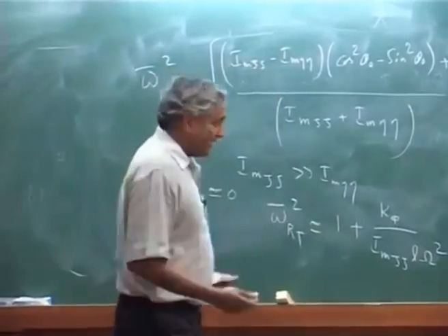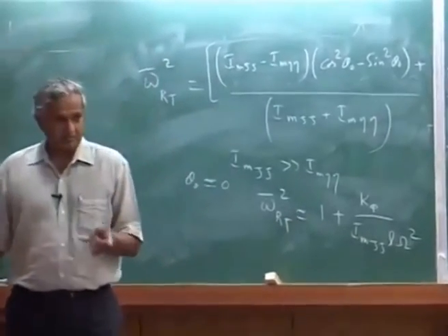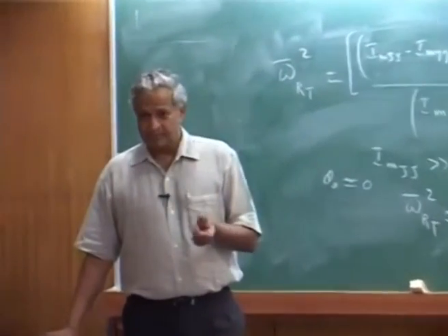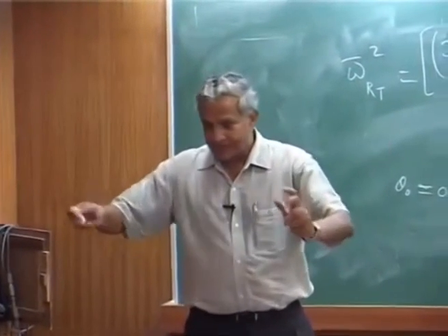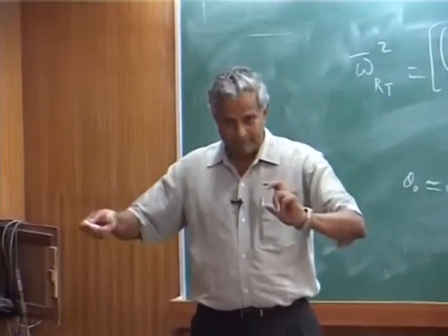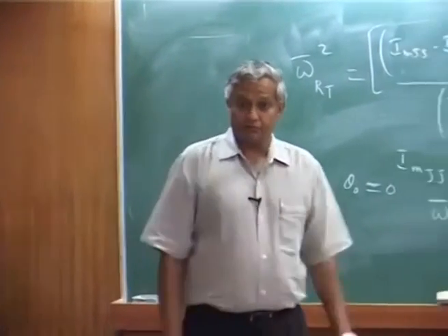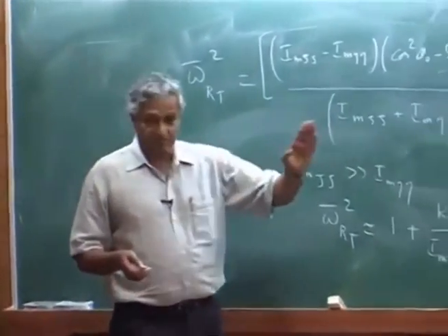So usually you try to design the control rod stiffness to be stiff. But if you take an actual blade, you have the control rod stiffness and you have the elastic GJ, the twistness of the blade, and both will contribute to that. For those equations you have to write the elastic blade. Here we assume the rigid blade.